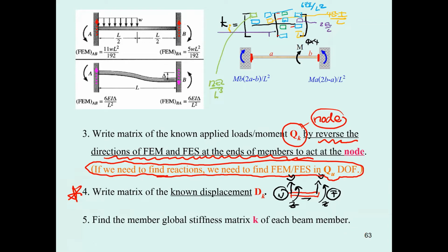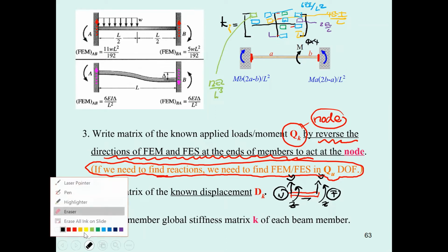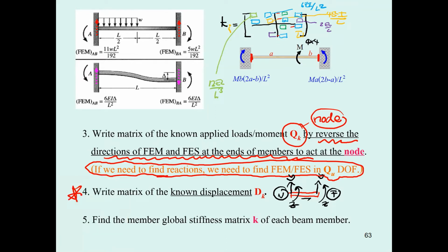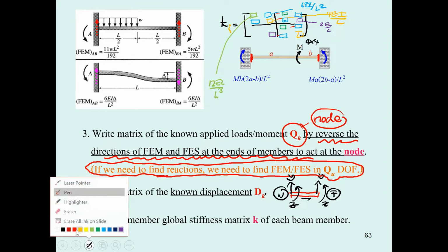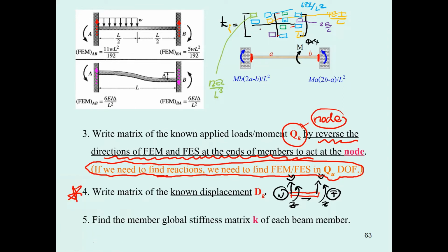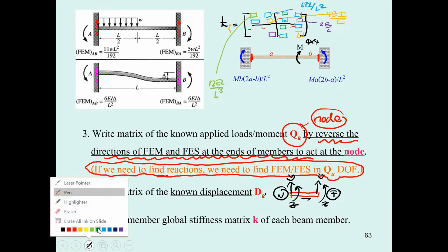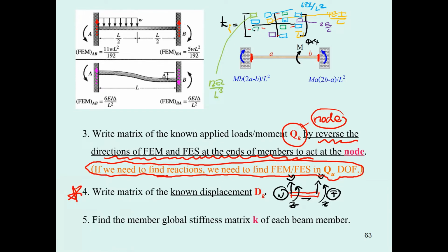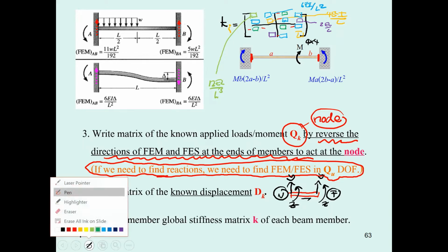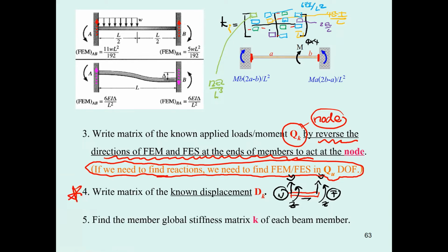And since this matrix is a symmetric matrix, you just put the purple into this position, and then copy everything that you have from the diagonal portion and put it over here. That is going to be the way you put together your K matrix. Okay, follow what I'm saying. It's going to require practice.